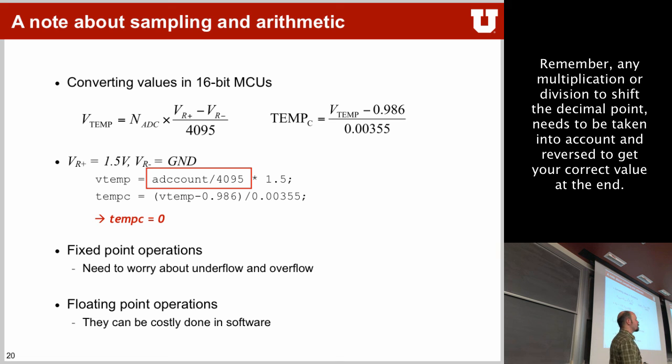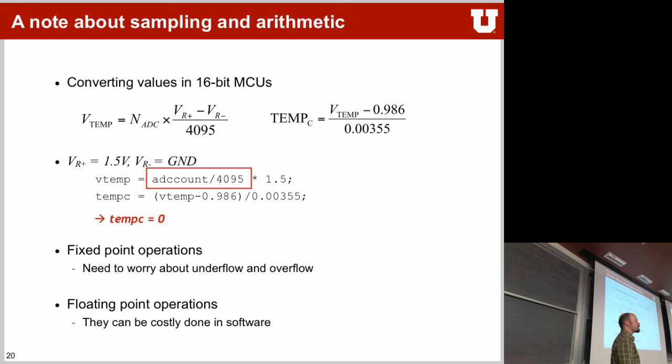Or you just say, okay, instead of having integer counts, we say it's now millivolts, right? So yes, you could multiply this first thing by 1,000, and then you get millivolt counts. And then you have to adjust this number down here again in order to do another calculation. But you can basically shift the decimal point around as long as you keep track of what units you're actually calculating in, if you want to avoid floating points. Okay, any questions?